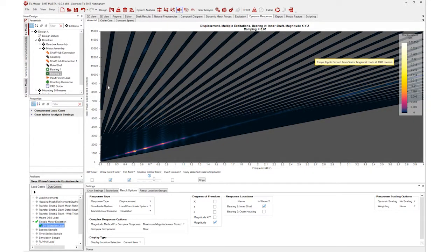Okay, so you can see, for example, if I hover over a particular order, it will show me what that is. So if I hover over this one, which is actually showing me an excitation, I can very clearly see that it's the 24th harmonic, order 24, which is what we would expect because of the 24 teeth. And then hypothetically, if I wanted to do a bit more analysis on these, just to very quickly show you, let's say we were comparing this to acceleration, so we can view the results in a slightly different format.